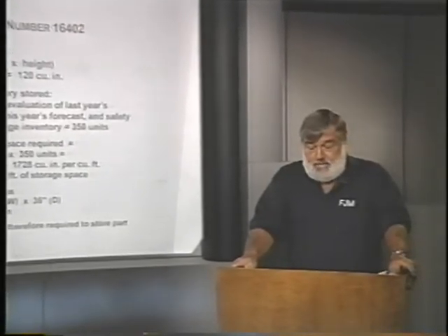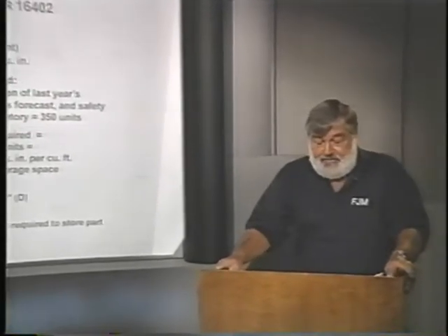Since bin number 5 is providing us 36 cubic feet, and we actually need 25 cubic feet for our lot size that we're going to carry, then we would need one number 5 bin for part number 16402. Now these steps that we've gone through, steps 1 to 4, are very easy to identify in a little PC-based system.